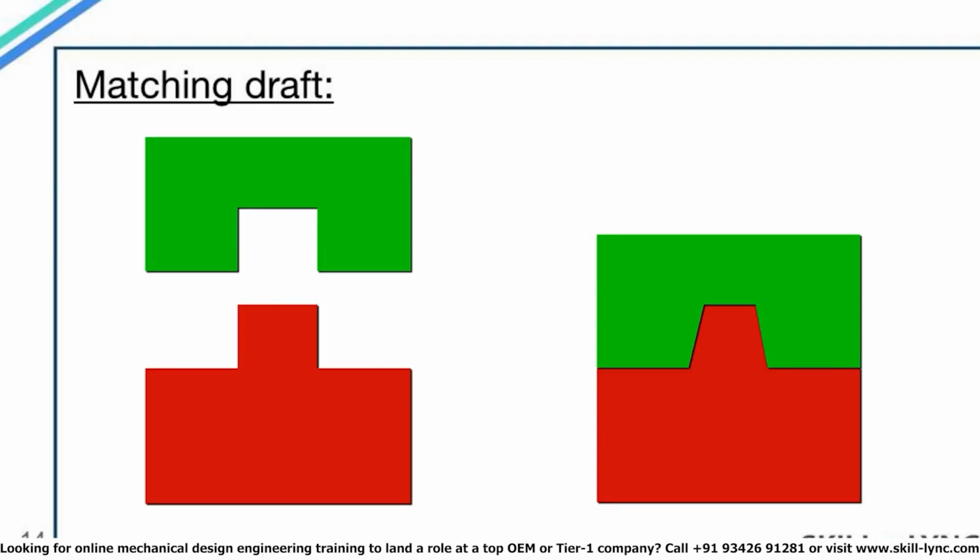So when this process takes place repeatedly, the core cavity blocks will get damaged, and once the blocks are damaged, the plastic material will seep through the cracks in the mold blocks, resulting in flashes. Flashes is the defect where the extra material is formed along with the component.